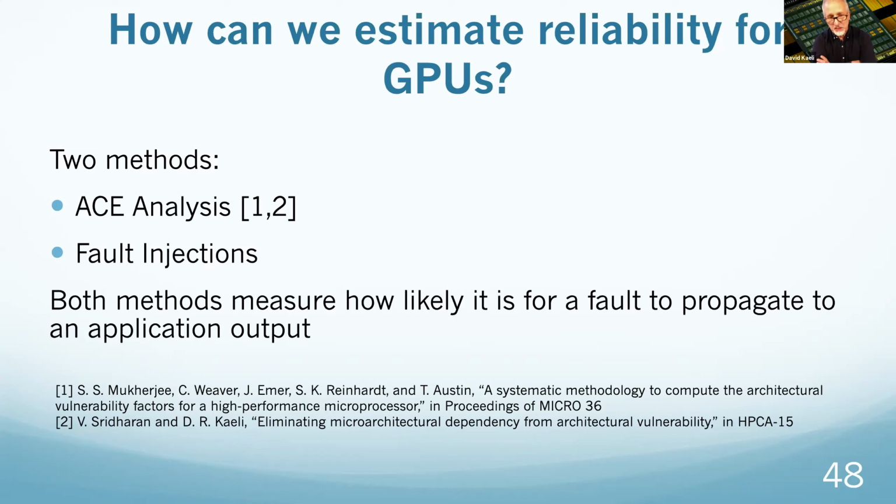Fault injection is another technique where I take a live system and I say, oh, let's change that bit. Let's change that bit. Back in the day when I was working at IBM on mainframes, I built something called a bug box that basically could go off and flip bits at various points in time based on the state of the system, and inject very detailed faults and see how the system reacted. So fault injection you can do on live systems, you can do it in simulation, but it requires statistical significance to actually have enough injections to get confidence in your results.